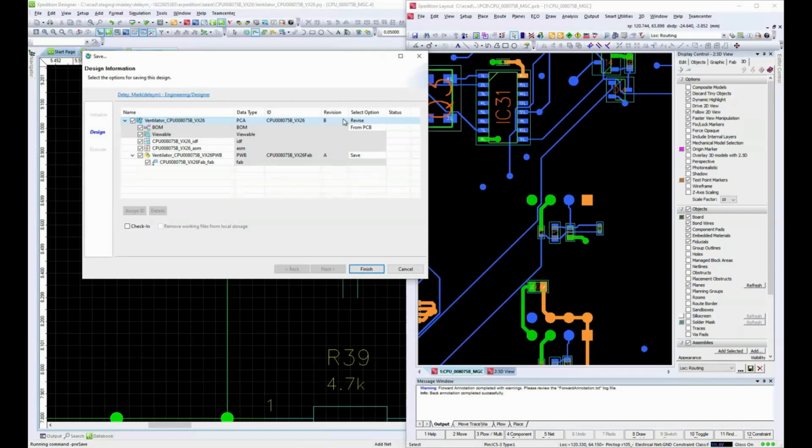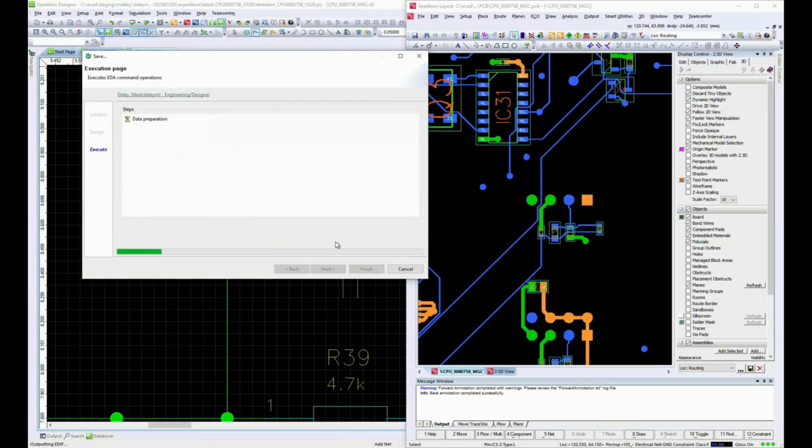For the manufacturing documentation, I have a little bit more options to drive that. I can save, revise, save as if I need to create new documents for a different version of the document, or I can save over existing documents. In this case, I also want to do a revision on it. So again, if I click Revise, it knows the revision control rules and will automatically go to B. If I'm done, I simply check it in and say Clean up my engineering workspace and click Finish, and the vault will be updated with the new data, and it will send a whole package there.